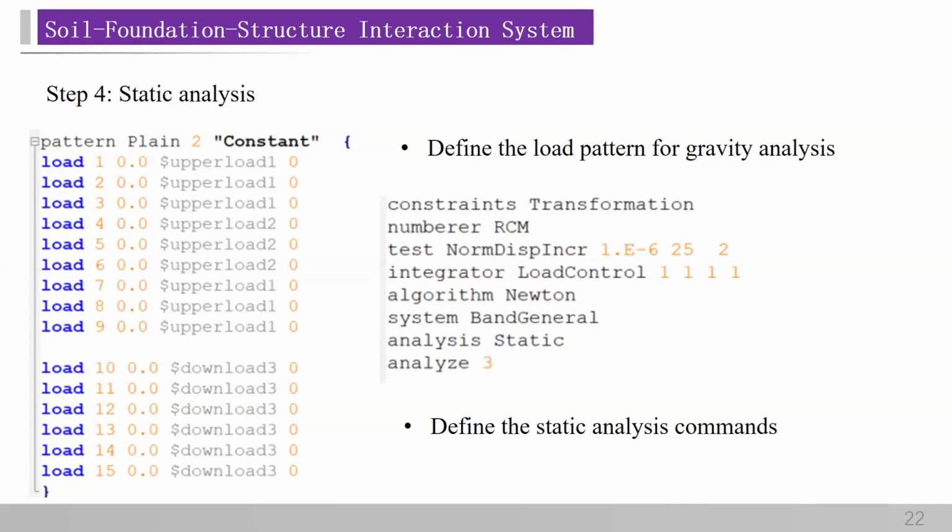And inside the load pattern, we use the load command to apply the nodal force. The numbers following the command indicate the tag of the node and the force in the X, Y, and the rotation directions. Then we should use these commands to perform the static analysis for this gravity load.